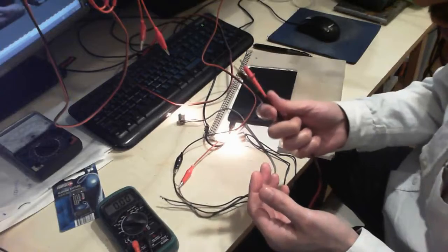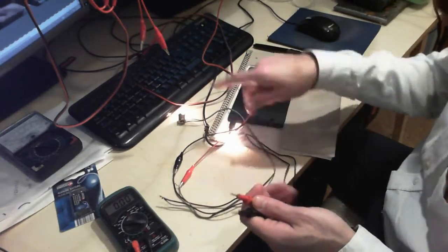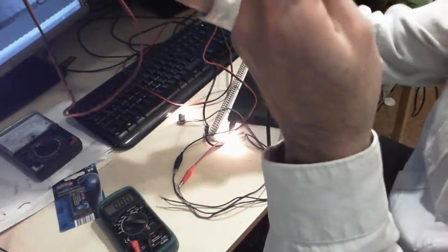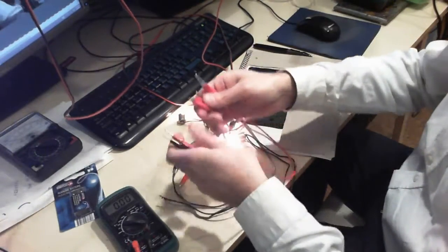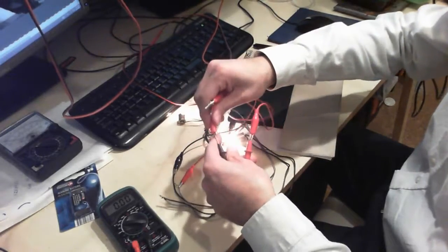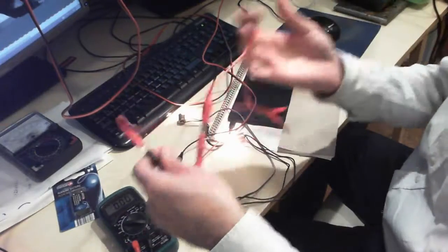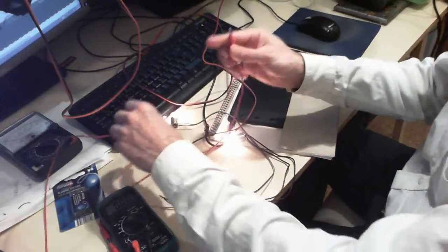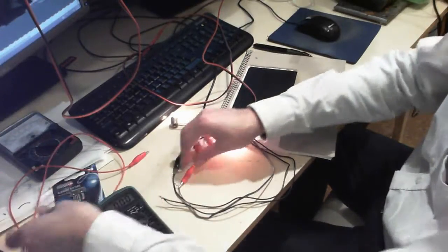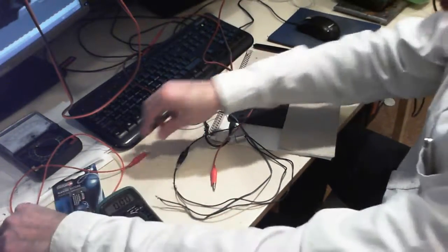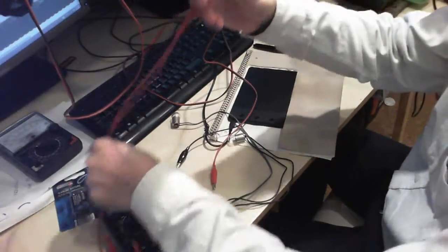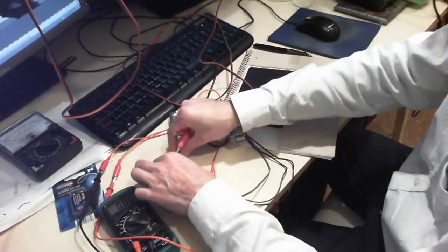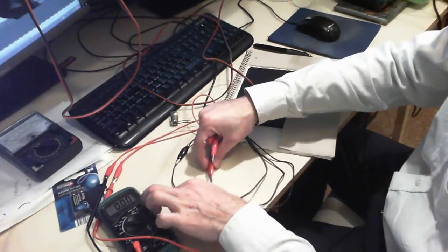So the amp meter has to be connected in series with the load. So what I need to do here is I'm going to connect these alligator clips to this amp meter, and now this lead is the positive probe of my amp meter. So I disconnect this circuit over here, and now the circuit is broken. So now this amp meter has to go between the load and the power supply. I have not touched this. I have disconnected only one wire here.